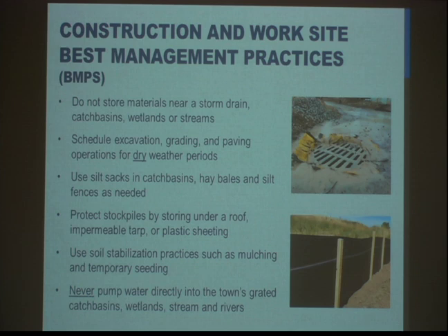Schedule excavation, and this is for in-house too, for when it's not going to be raining. Use silt sacks and catch basins, hay bales, and fences around construction sites. Protect our stockpiles. Use soil stabilization and temporary seeding if needed for large piles. And another big one is never pump water directly into the town's catch basin, which people do. Contractors do that, and I'm sure we don't do that.